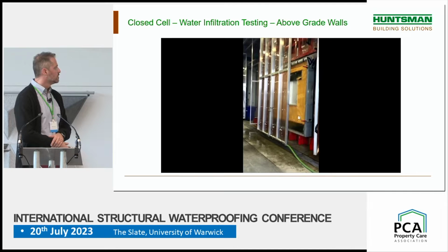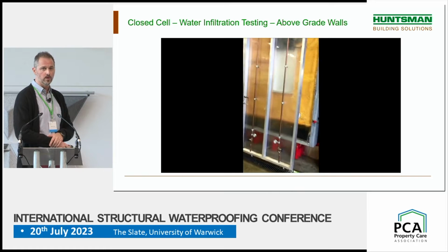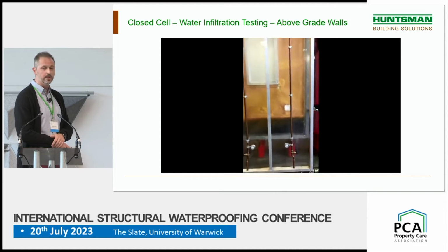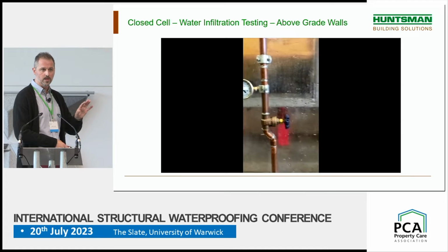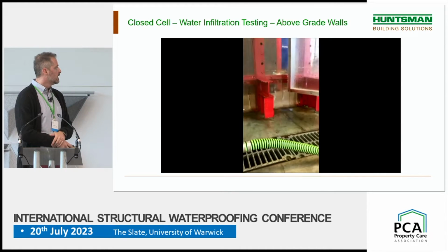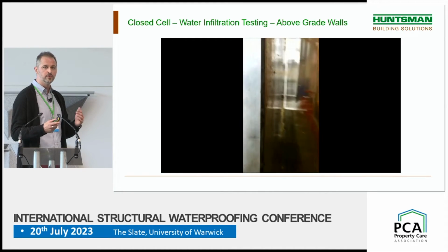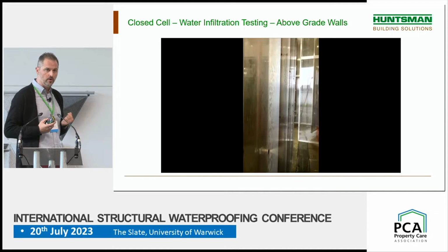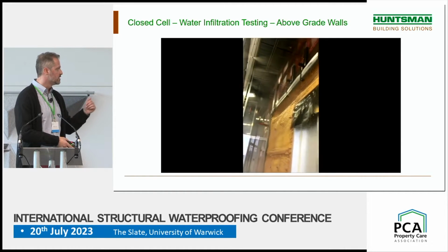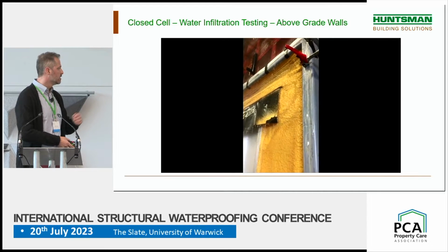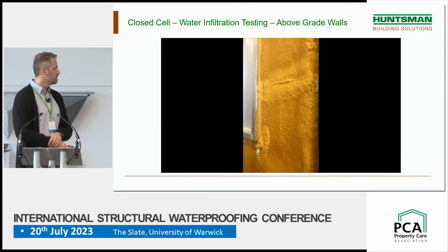Okay, a quick video now. So this is what I was discussing when I was talking about water-resistive barrier for above-grade wall assemblies. This is the ASTM E331 testing where we spray a huge amount of water on the wall assembly. So spray foam is exposed directly to the water, and all along this testing, there's a negative pressure of 300 Pascal that is trying to pull water inside the wall assembly. And as you can see, there are many details like penetrations, like a window, brick ties, Z-girt, and vents. All of these are kind of the worst scenario for a wall assembly like this.